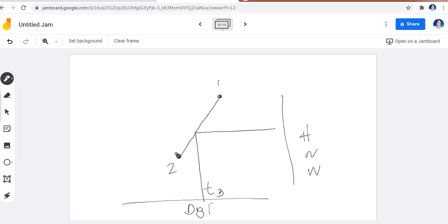This will correspond to a value which is 65.5, more or less, 65.5 degrees Fahrenheit. As for the dew point temperature, that would be the dew point temperature that you're going to read here, because we're reading the dew point temperature horizontally, and there's another line here in your psychrometric chart for that. If I'm not mistaken, actually the dew point temperature is before the reading for the humidity. That's how simple it is. You connect the two, you solve for H3. This is H3 value, and then you have the T3 read from the psychrometric chart.